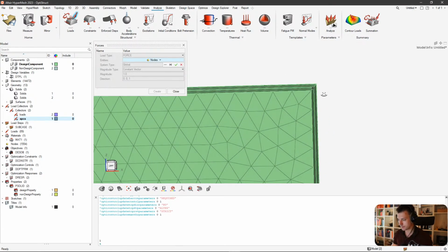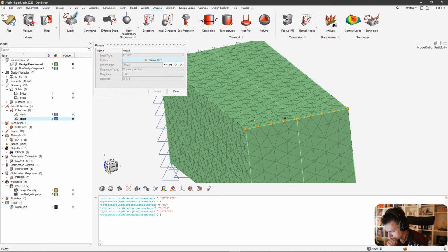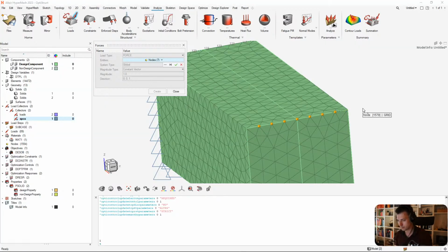We will do just something like select the nodes here and do an evenly distributed load. So 9 nodes were done here. Let's think about how to distribute them, because you have a free edge here. I think what would be appropriate is to select 7 nodes here and do a little calculation. 1000 divided by 7 would be 142.8. So let's do it like that. Ah, no, sorry.